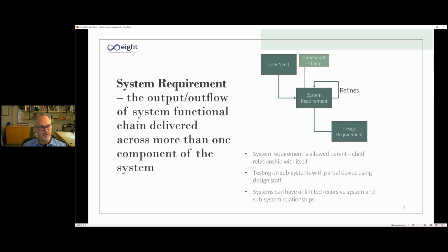So you can imagine if I have a pump and we say the pump, its function is to deliver pressure, but let's say we have to deliver a pressure that's 120 psi plus or minus a tenth of a psi, and to achieve that, it's not just a pump. Now we have a proportional valve and we have some control and whatever. And to get that output, we have to have another subsystem inside of it, right?